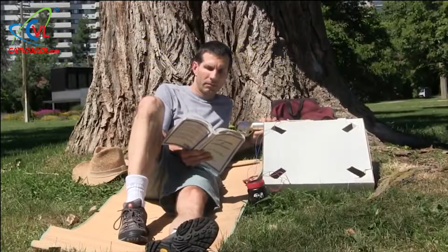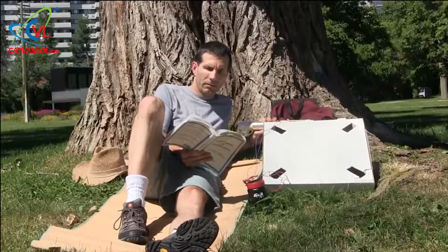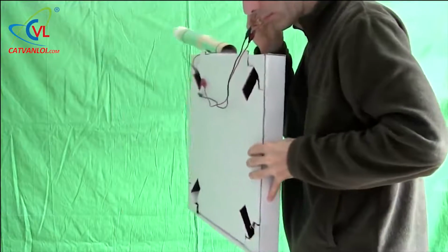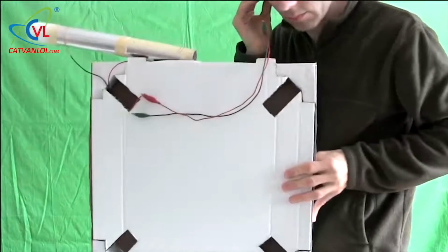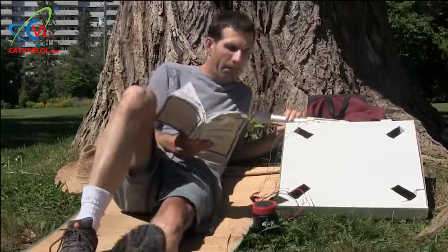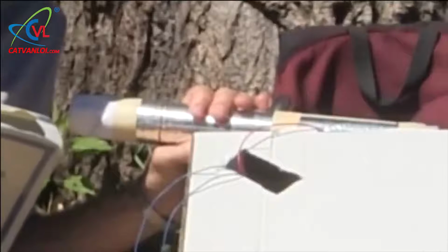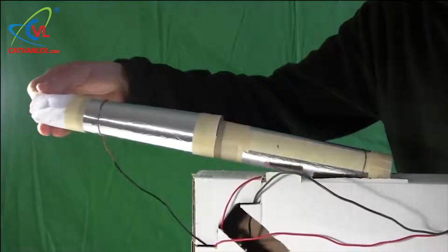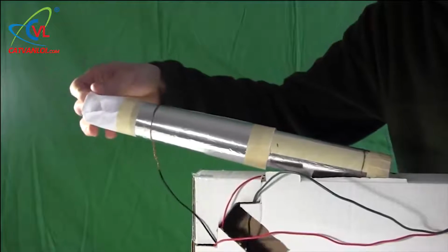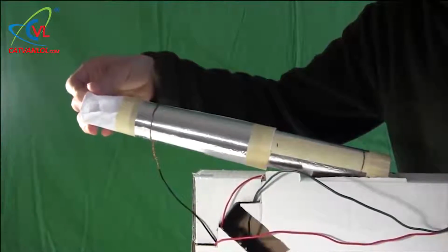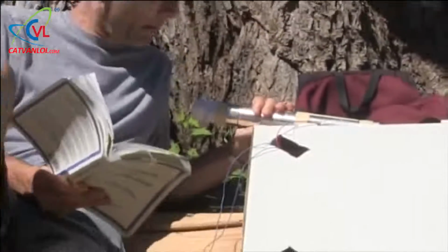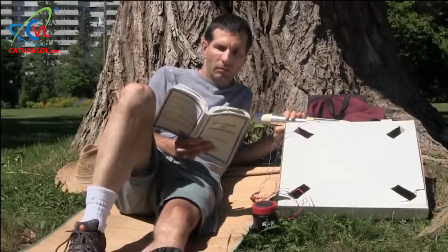If the current and voltage aren't too high that you get hurt, then your own body can sometimes act as an okay ground. An example where I've done that is with this portable pizza box crystal radio. It's portable because it doesn't need a ground to work, but it works better with one. And if you look closely here, you'll see my hand is on this capacitor plate. The capacitor is one aluminum foil cylinder that slides around another one, and with paper in between. Making a lot of skin contact with the outer cylinder lets it conduct charge to my hand and body.